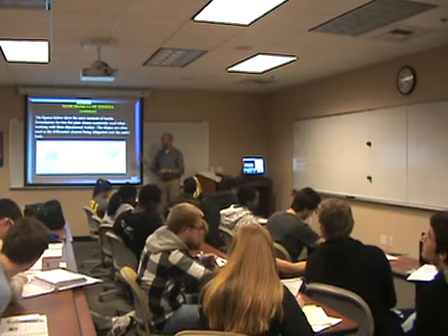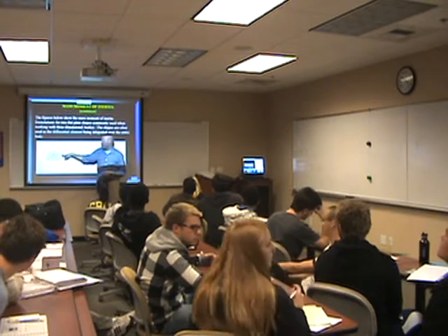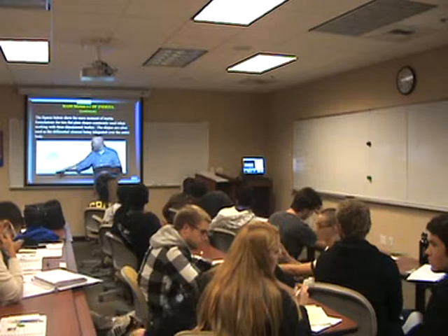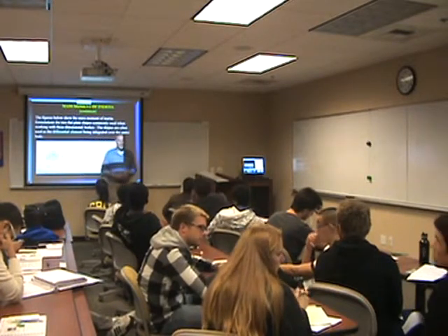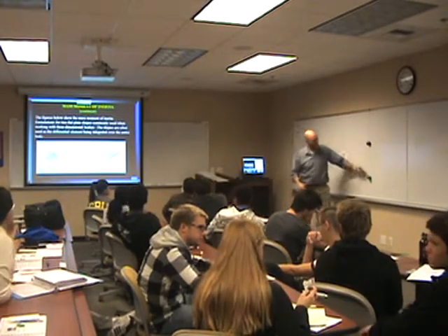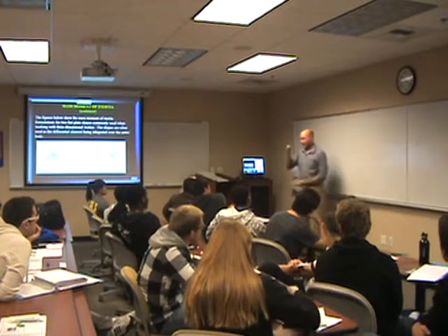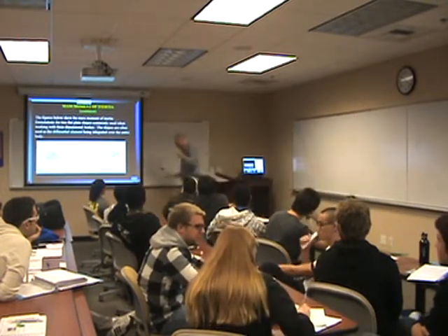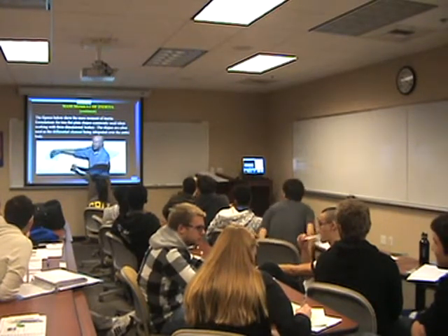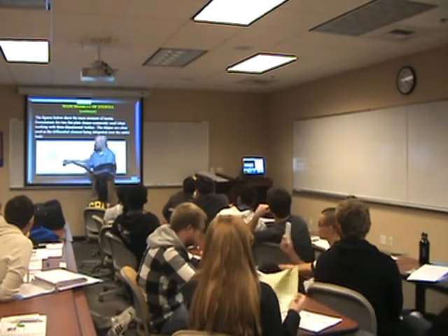So we can do the calculus, and for a thin cylindrical disk, we have Ixx equals Iyy equals 1/4 mr squared. Izz is equal to 1/2 mr squared. What does Izz mean? So here's our disk. Izz is if we're rotating about like this. Rotating about like how we think a yo-yo should rotate. That would be Izz, rotating about an axis here.